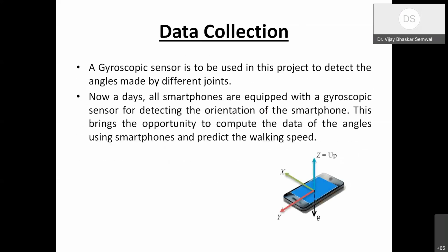Okay. So for our experimental purpose, we have used the Arduino Nano BLE Sense, which I will show on the second page of the talk. But what are the gyroscope, accelerometer, and magnetometer doing? In a sensor, you have three axes, X, Y, and Z. The gyroscope tells the rotation around the X-axis, Y-axis, and Z-axis. There is G-force also. So you use it to detect the angle made by the different joints.